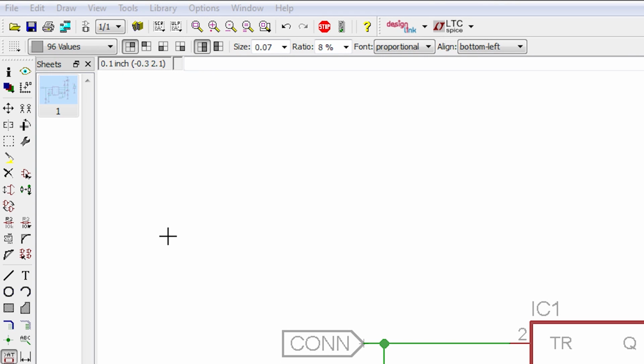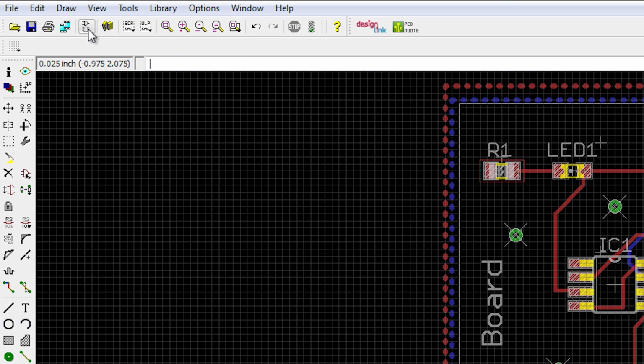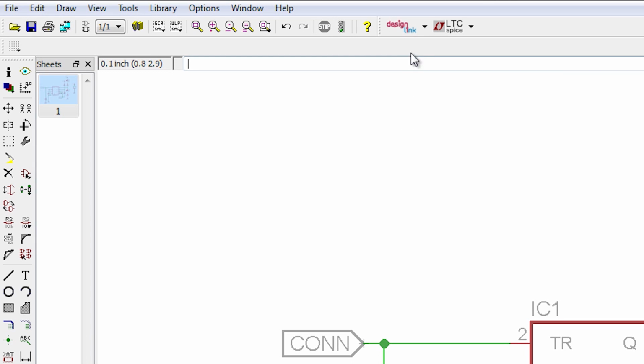Of course, you can also manually generate a BOM for DigiKey or Mouser or any other electronics distributor, and I'll often do that. Or you can also go find plenty of user scripts that plug into Eagle that generate BOMs for all kinds of suppliers. But we'll use the Design Link tool because it's built in and it's pretty easy. Remember, to switch back and forth between your schematic and board layout, you can click this little button on the top left corner. So go to the schematic, and next to Design Link, click the little drop-down arrow and choose Schematic.